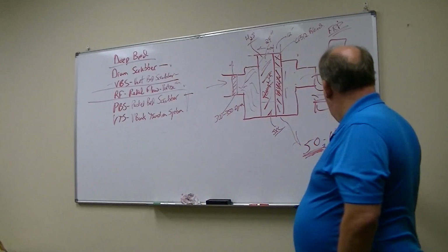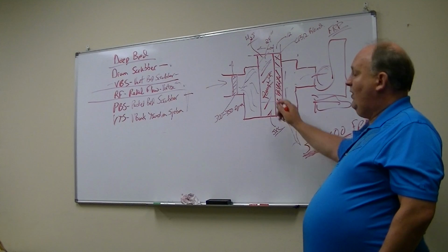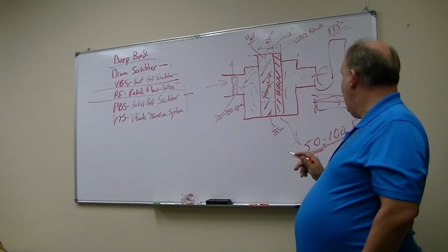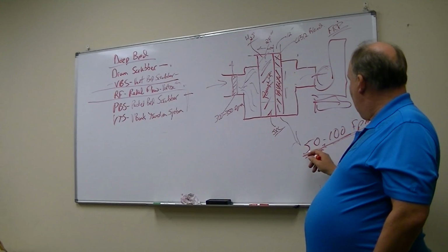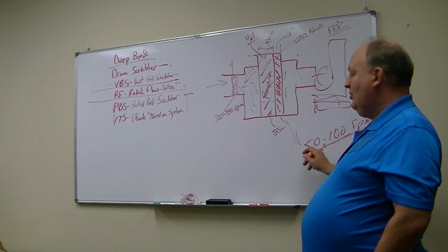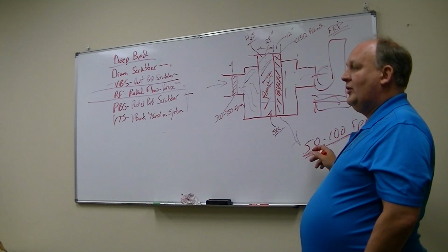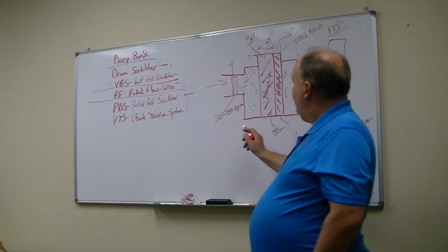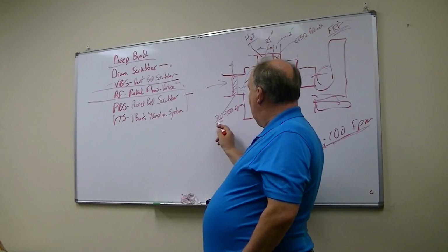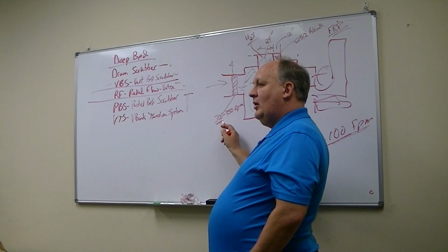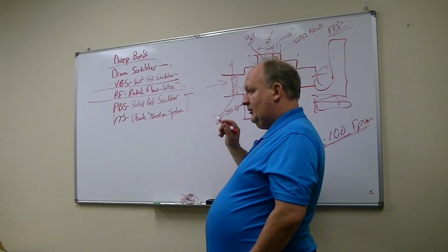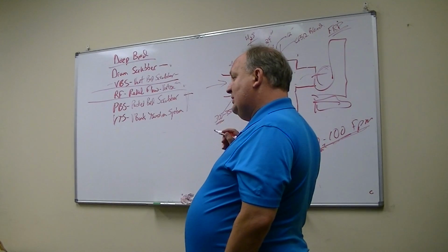Much faster than we're sending the air through here. Now keep in mind, we target for 50, but you could go down to 20 feet per minute on the media if you wanted to, okay? But there's actually a lower limit that we don't want to go too much below because of the mist and grease filter. So here's how a mist and grease filter works.